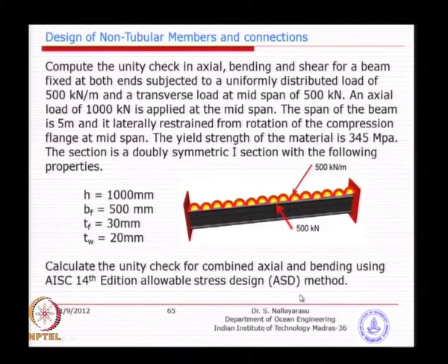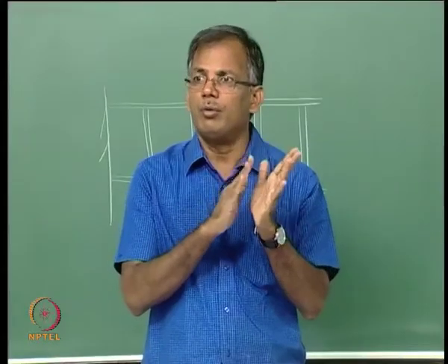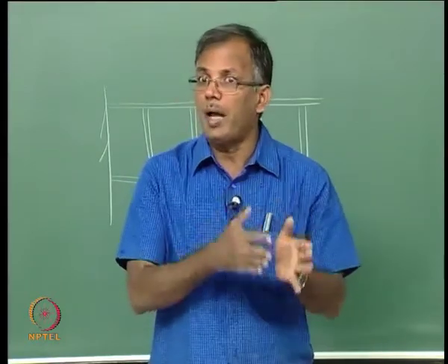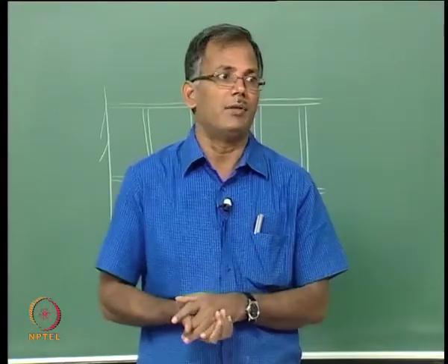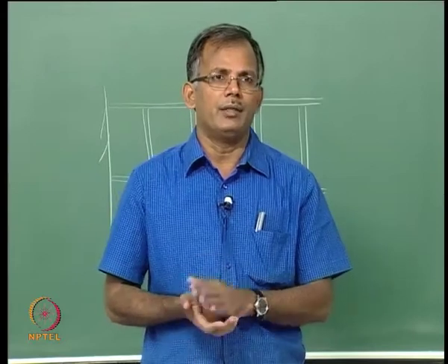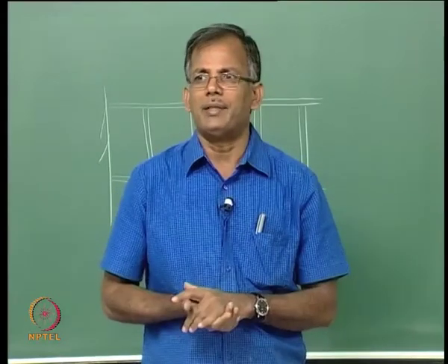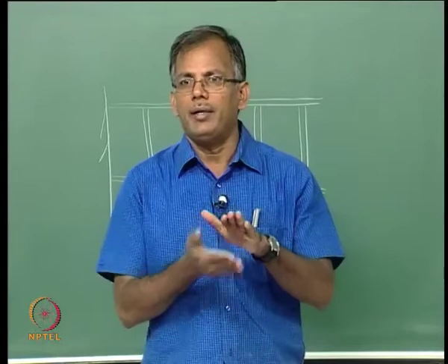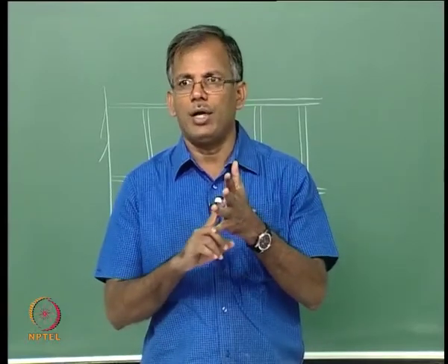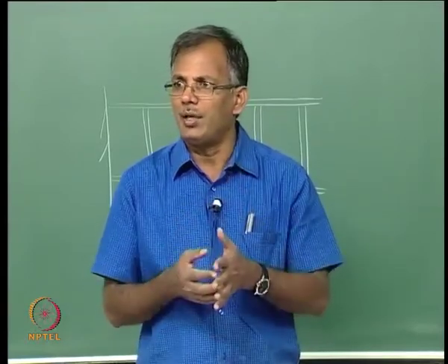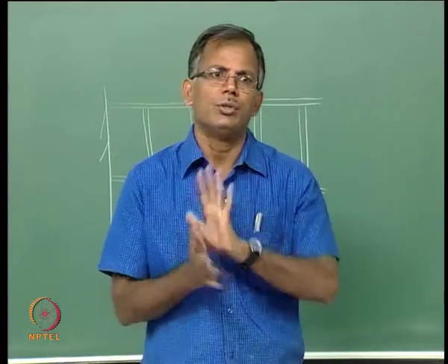We now have the idea of how the LRFD also works. In parallel we have worked out, most of the equations are given to you, basically the difference is only in the capacity calculation and unity check. Whether it is the buckling calculations or the allowable stress calculations or allowable capacity calculations, every one of them is almost similar.